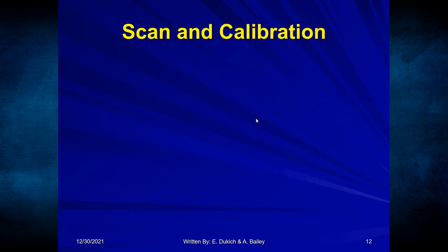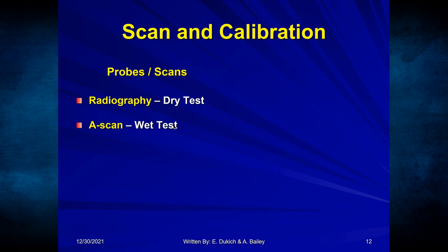Now, when I'm determining the scanner and the calibration standard, well, for radiography, it's a dry test. I take a piece of film, put it on the component, and use an X-ray machine to capture the information. Conventional ultrasonics is typically a wet test. I just take ultrasonic gel and use a contact test, or I can squirt water or immerse the entire component in water.